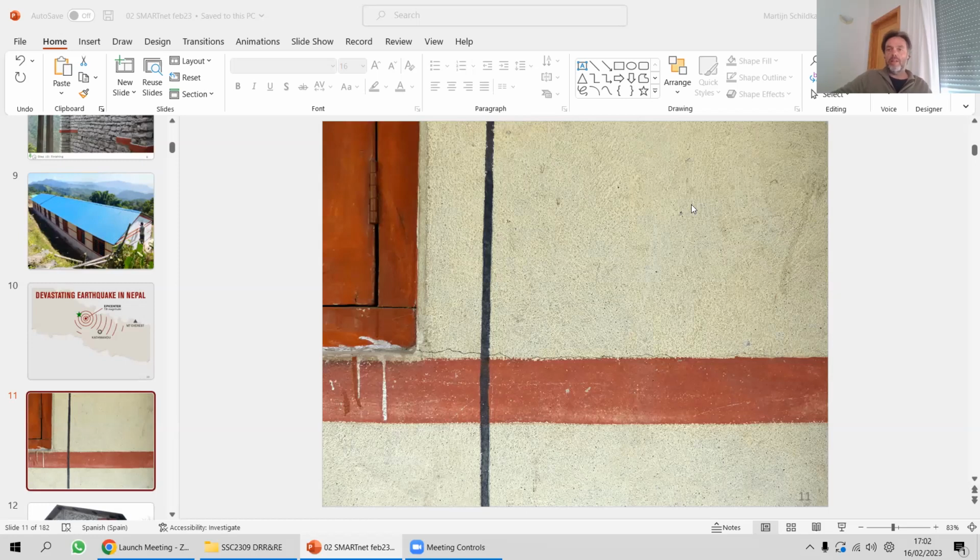Any information about the seismic design of adobe? Yeah, okay. Back a few posts, there is beautiful research done in Peru. What I can say about it in two words is that it has fairly limited dimensions. But that's the consequence of working with a brittle material, and then with some geomesh and some tying of meshes around it, it really can withstand quite heavy earthquakes. So if you go back a few posts and maybe contact each other directly, yes, it can be done.